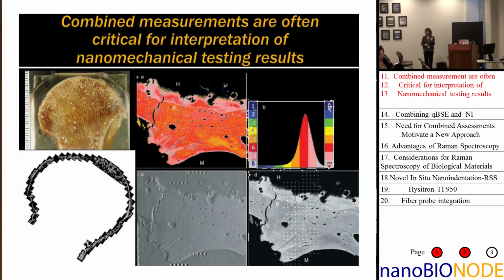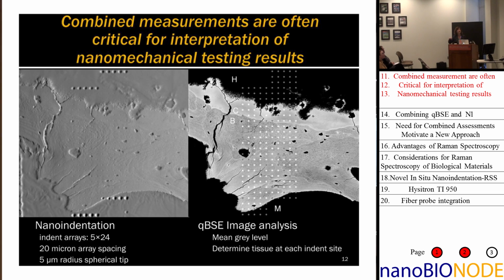So now I take that over to my nanoindenter, where I maybe have a 20x objective, and I try to find a region that I found on my SEM. I find a suitable region like this. I put some indent arrays, which are big marker indents. My real indents are in the middle. I've plotted that out over here over the quantitative backscatter electron image. And then I have to come up with some MATLAB code, or we used to use more crude methods in the old days, to correlate the spots. So here this is just showing, again, my nanoindents at higher magnification, and then where they lie on my regions here.